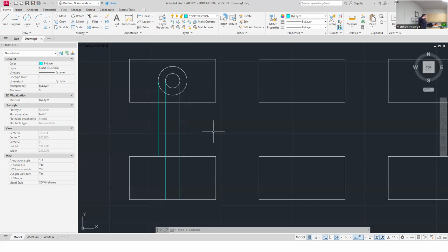But a lot of times that type of fastener is being passed around, we like to sink them into the material. The head of that we don't like. It's a really tall head. They're really strong. They can hold a lot of torque. They're a really strong bolt, and the head has a lot of power in it essentially. But they're really large. Like that head is really large, where the tooling can be to remove it, engagement. So we don't always like that to be sticking out above the material.